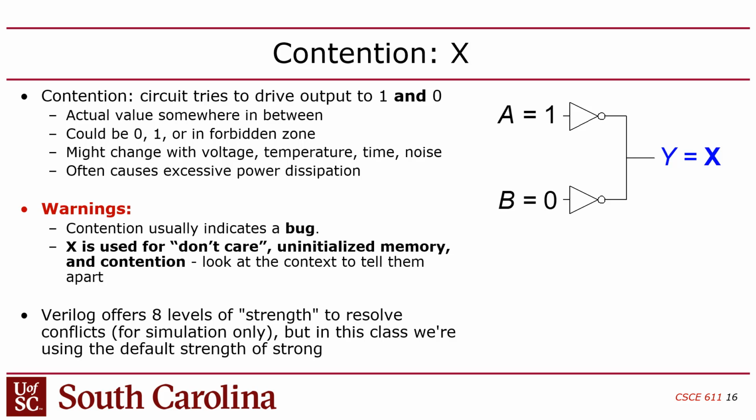You might say, well, wait a minute, that's not the case in circuits in general. In circuits, you can have as many voltage sources as you want. The problem is that in digital design, these gates are designed to create a low impedance path to either the power supply or ground on their output, right? You have transistors that either pull the output up to VDD with basically a 1 ohm resistance to the power supply, or connect it down to ground with like a 1 ohm resistance, right?